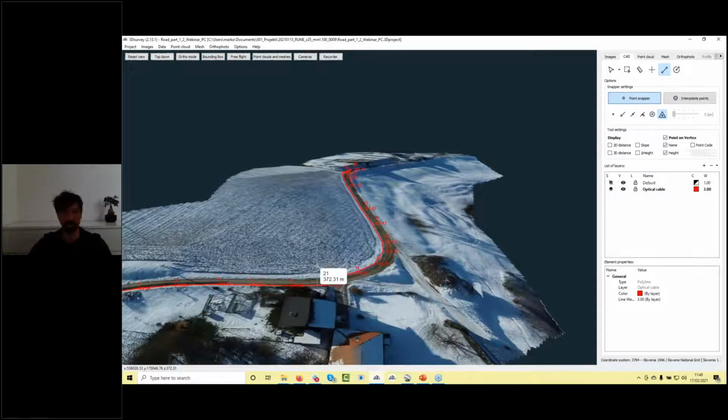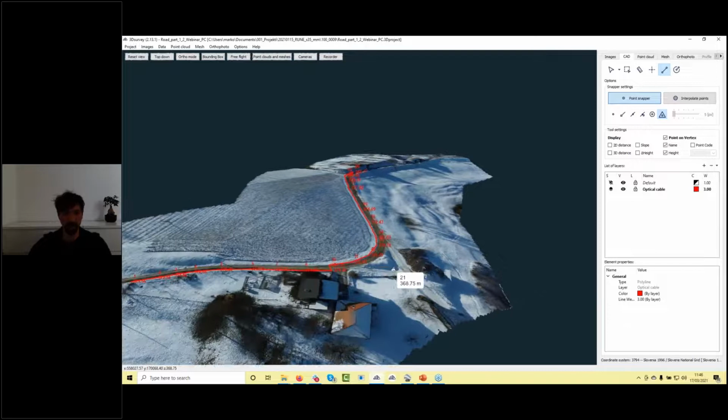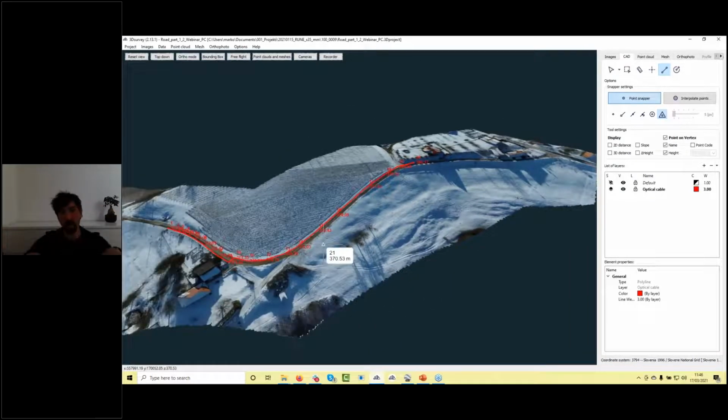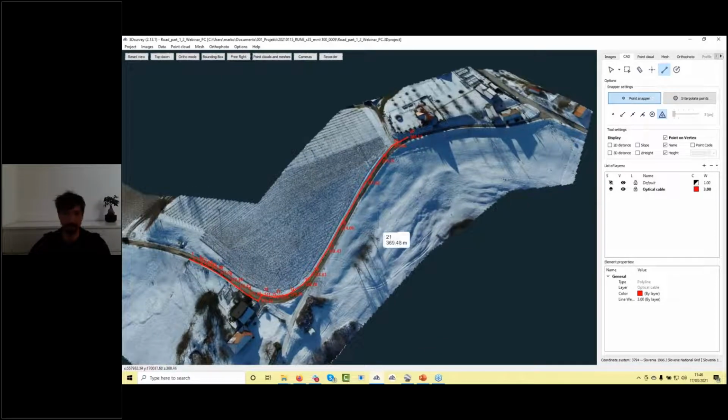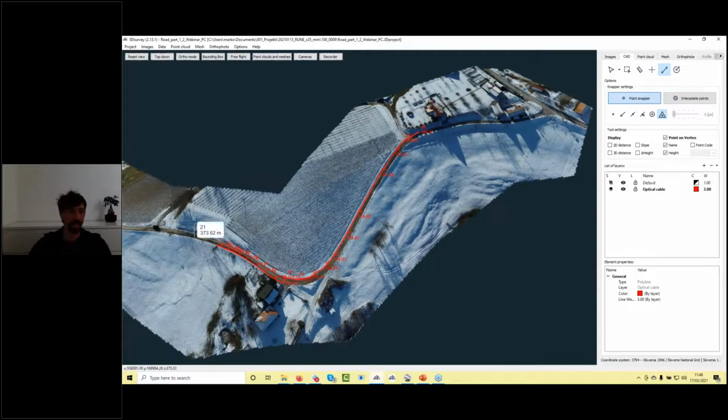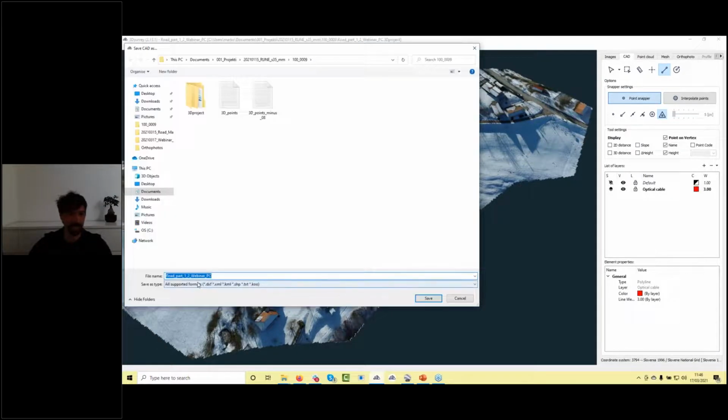Now we know that usually the power line, the optical cable, the telephone line or anything like that are buried in the earth at least, I don't know, 0.8 meter deep. If you would like to move these points, so lower the height of these points, there's a trick actually. What you can do is save those points as point cloud points. So we have CAD data, and we will save CAD as 3D points, optical, let's say, like so.